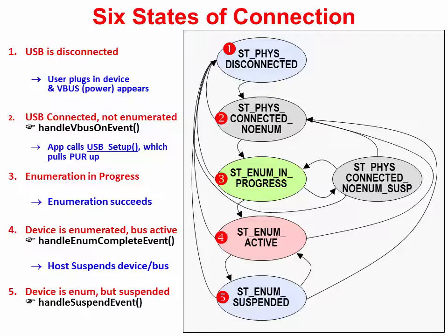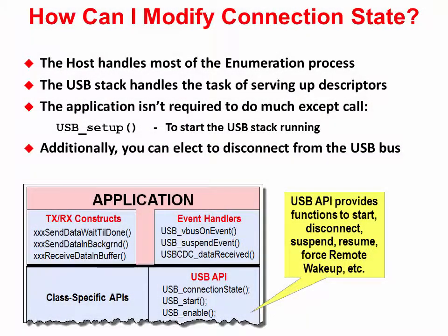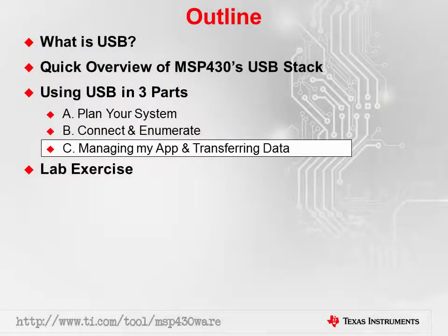You can do this by adding code to the suspend event handler function. As just a quick reminder, yes, you can affect the connection state. While you don't control the bus transfers, as only the host can do that, you can use the stack's functions to connect, disconnect, start, stop, and even suspend your own connection. The third part, managing my app and transferring data.